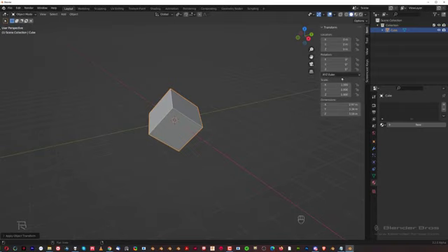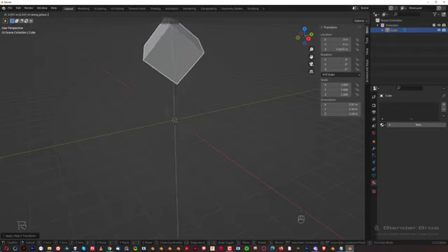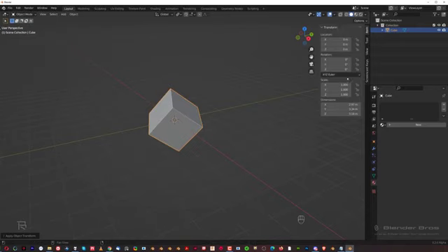You can now see that the rotation got reset, and this is now the global and local orientation of that object, meaning even if I press G, Z, Z, it will not do anything because there is no local orientation. It's been applied. So here you can check whether your object is rotated, whether rotation or scale, for example, was applied. Scale is a very important subject.